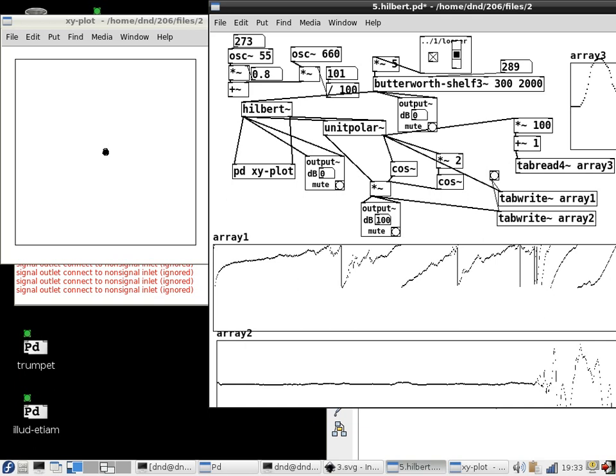This kind of control. What this is doing is changing the Butterworth filter. It's a shelving filter that has two frequency extremes, and if you drop the roll-off frequency, that has the effect of lowering the high frequencies as well as leveling off, as well as changing where it starts rolling off, obviously. And so that's the sort of whammy bar that's going on here.